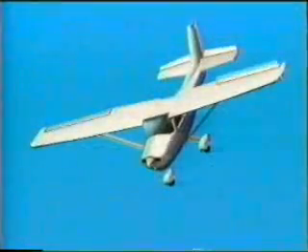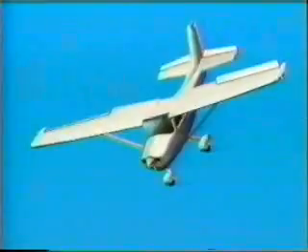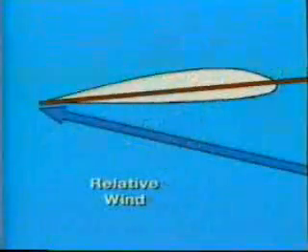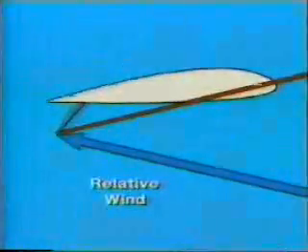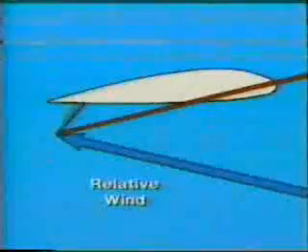During the recovery process of most general aviation aircraft, the ailerons should be neutral. If aileron is applied in the direction opposite the turn, the chord line changes and actually increases the descending wing's angle of attack, amplifying the spin.